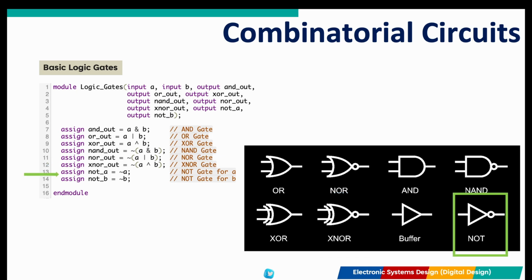Finally, the NOT gate or inverter. It is the simplest combinational element, taking a single input and producing its logical opposite. If you have an active high signal that needs to be active low, the NOT gate is your tool. Every complex combinational circuit we will study, from multiplexers to decoders to arithmetic logic units, is simply a strategic arrangement of these 7 gates.